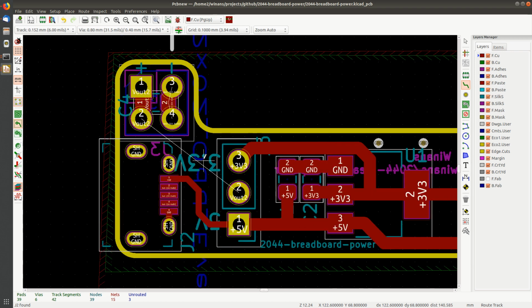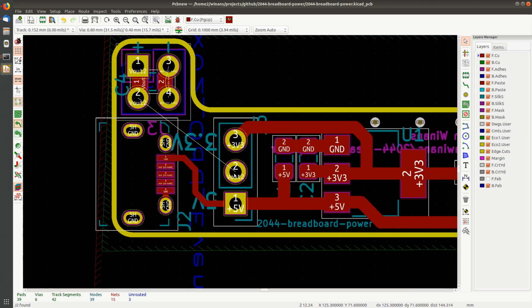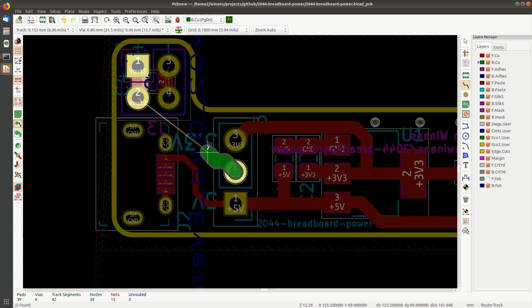All right, so now at this point, I could run a track right across here, but the metal on this is going to sit on the board. And when I heat things up or mess around when I'm putting it together, it could work its way through the solder mask and short out this output against the ground shielding on the case. So what I'm going to do is go to the bottom layer and just run the track on the bottom. That's all you've got to do. You click bottom, go grab yourself a track, and you're drawing now on the bottom layer.